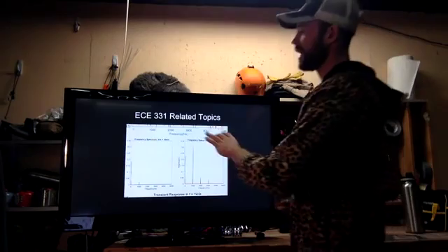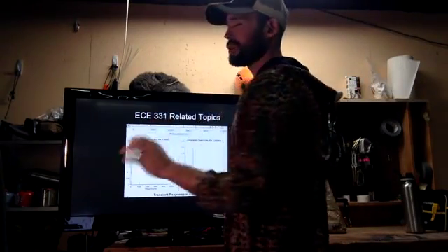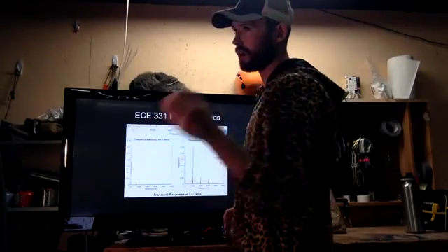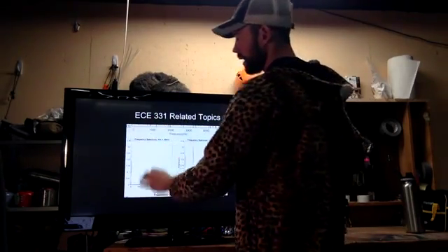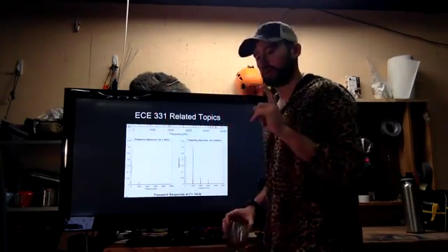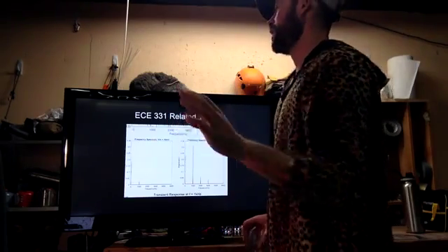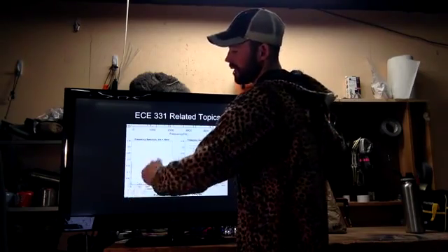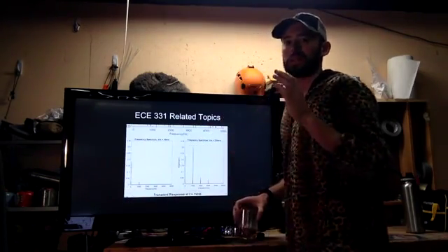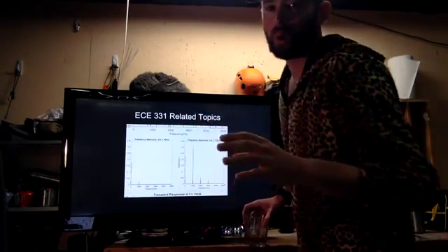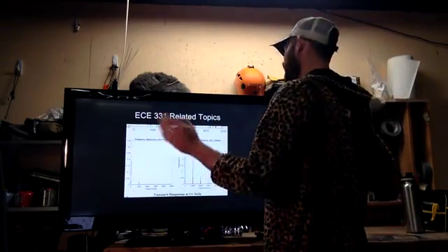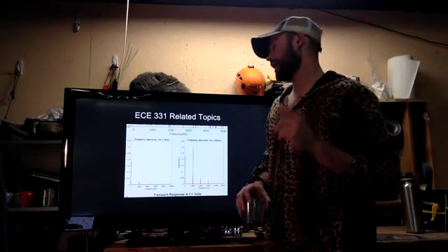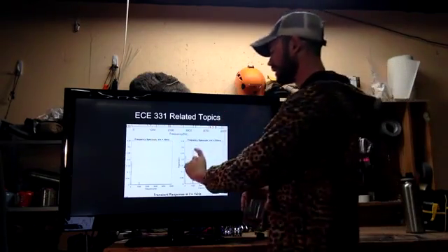So here we have our original 10 millivolt amplitude attached to our input signal. And we're dealing with a 1 kilohertz frequency. When we put that in, we have this small spike at 1K, and we have this spike at 0, which is our DC component. However, when we increase our Vin to 200 millivolts, we are actually creating harmonics in the system.